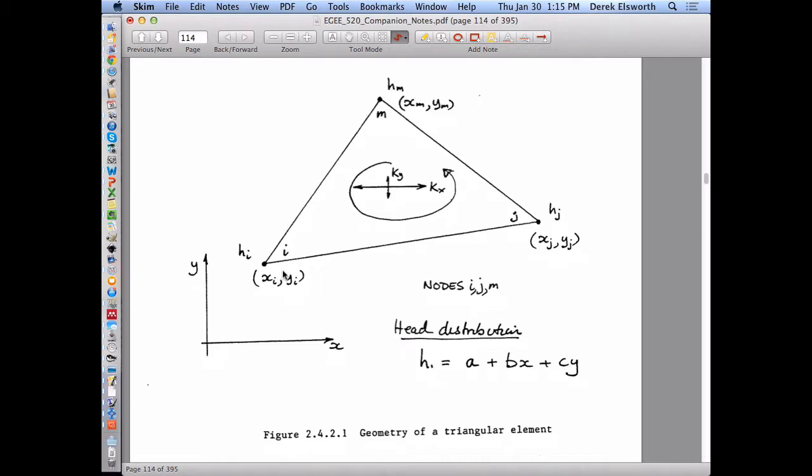And we know that in this we'll prescribe variables in each of the nodes. For this particular problem, we can either prescribe a flow rate at the node, Q value, or a head. If we prescribe one of them, then we'll solve for the other one. That's what we're attempting to do. So those are the two values, and those are embodied within Darcy's law. Q is equal to K delta H. So flow rate is related to head through some magnitude.